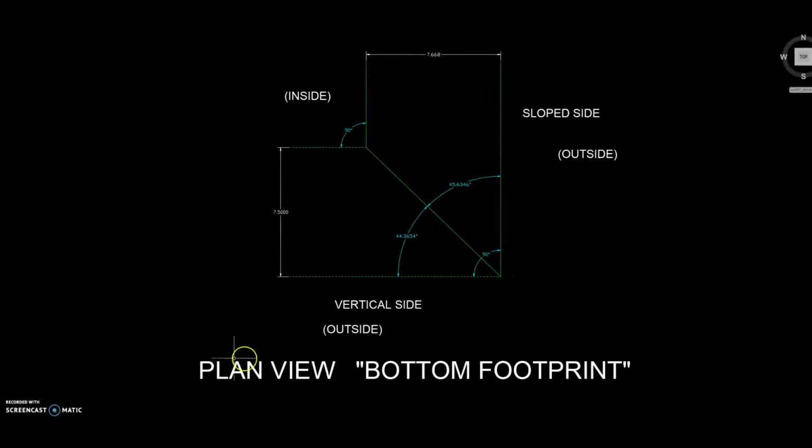With this done, we can all see that despite this being in plan view a 90-degree corner, the miter angles are unequal, as seen here. And just like that, right here we have the first piece of the information we were trying to get, the miter angles.